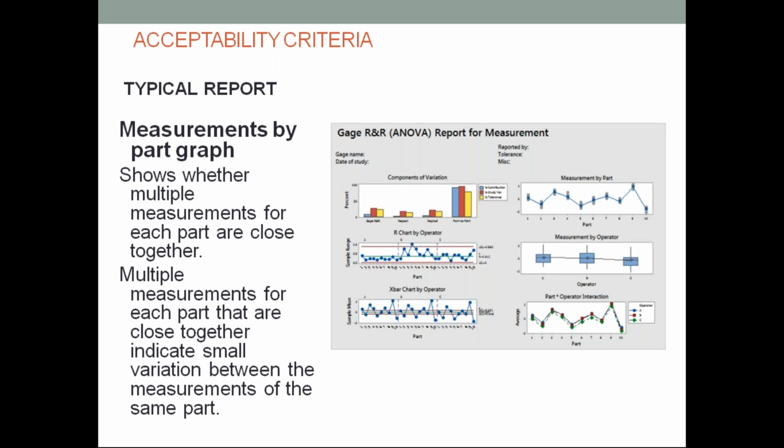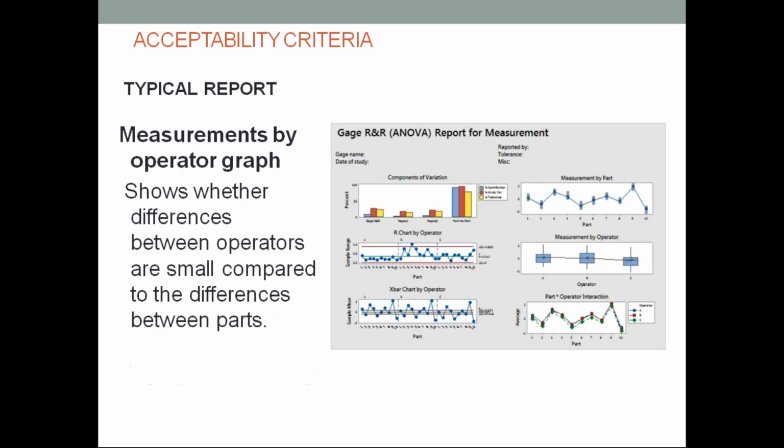Is there a surface condition? Is there a taper? Is it difficult to hold? What is different between that part and the ones that are measuring well? That's a key investigation you can have if you see that issue in that particular chart.